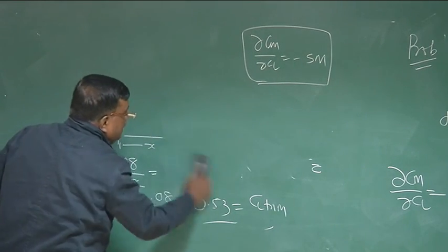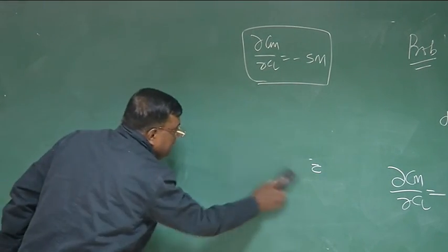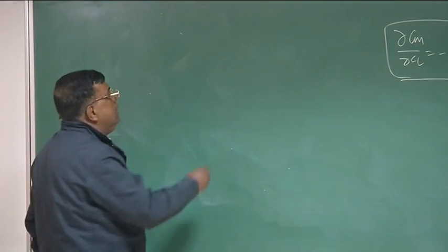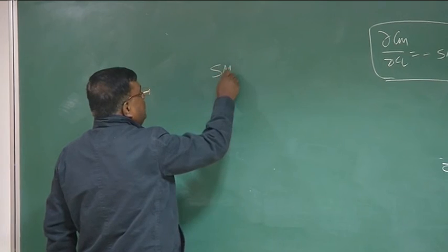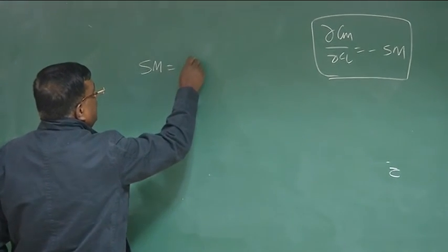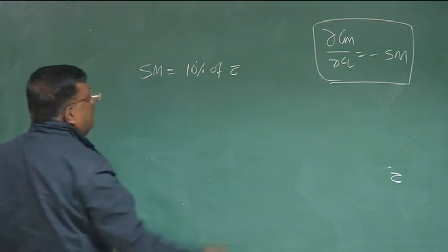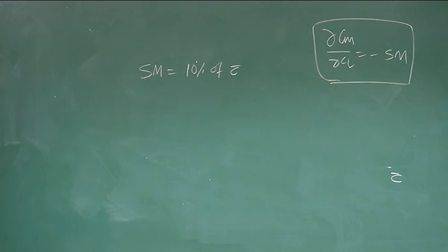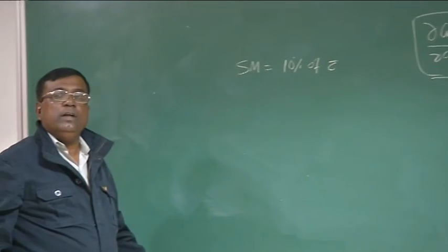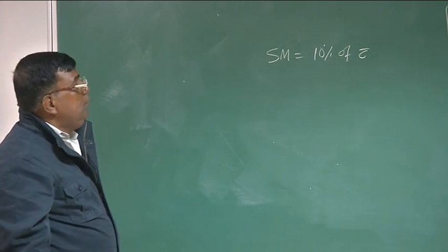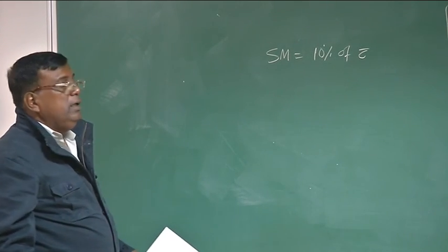When you are designing an aircraft, typically if you are designing a civil airplane, you design for a particular static margin, maybe 10% static margin. That is 10% of the mean aerodynamic chord. So now, if you want to select what is the wing area required, or what is the CL I should design for, you have a criterion.